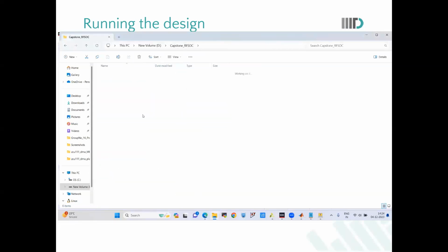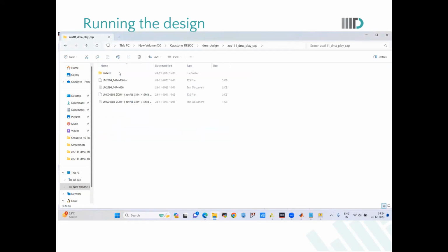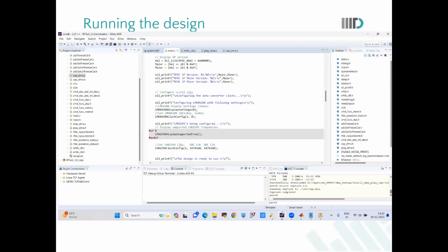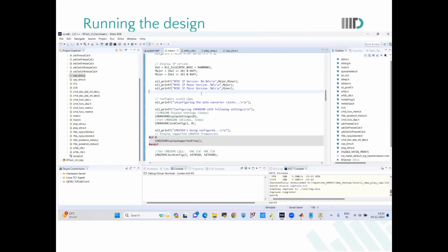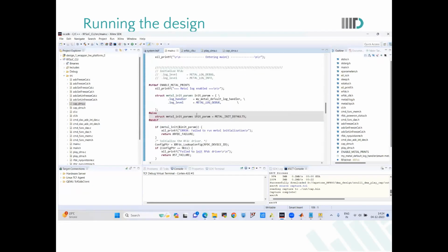Apart from this, you need to go to the clock files folder and put the register value file there for changing the clock. So there are three things you need to do. First change it in Vivado, then change it in the SDK code, and then put that file in the clock files folder.